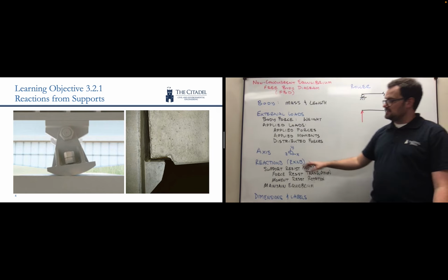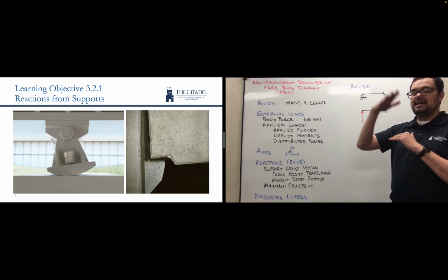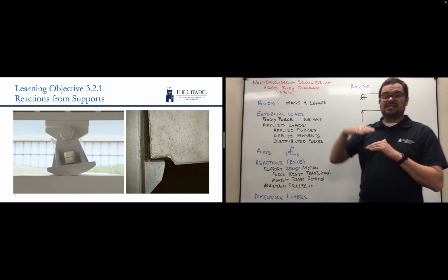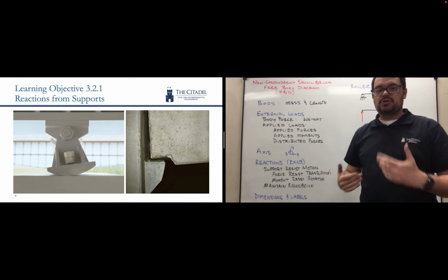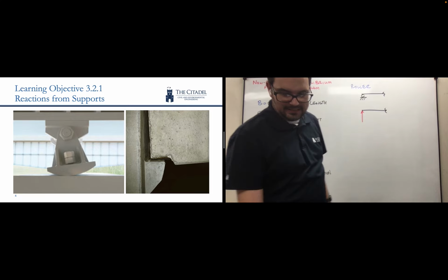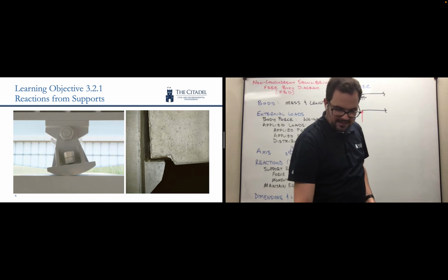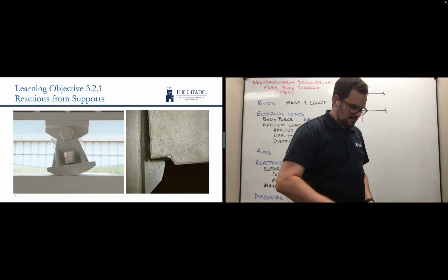All right, we've done the two translation terms. Does the force resist translation left and right? No, no force. Does it resist translation up and down? Yes, we get a force. Does it resist rotation? Well, no, it'll rock or roll. It's a rocker roller, so there's no moment there, which means that this is it for a roller, and we would get exactly one unknown. The idea behind a roller is that when we think about our potential models for this, a roller is just the same as a contact surface.